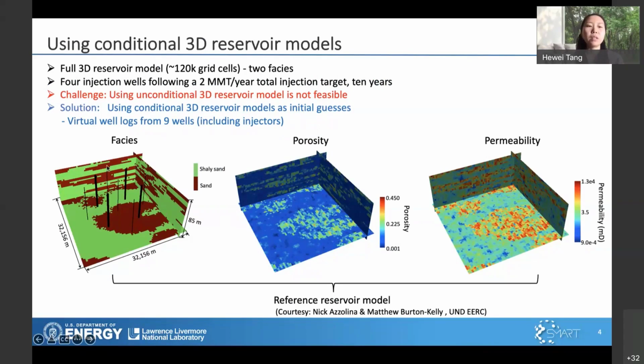I want to additionally mention that these 4 wells are actually connected to a single manifold at the tubing head. So they actually share the same tubing head pressure, and the injection rate will be allocated dynamically throughout the injection period, based on their injectivity. So it's actually a more complex boundary condition than fixed bottom hole pressure or fixed injection rate.